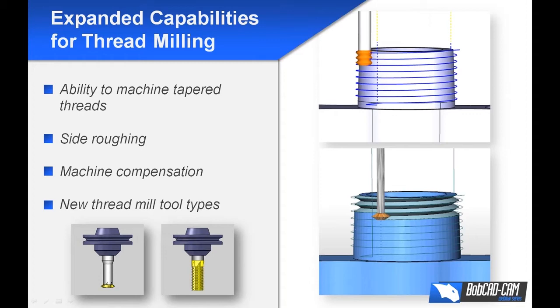All right. Give me one second. We have a question that's already in V5. You can select the solid from drilling. Yes, you can select the solid for drilling, but it doesn't break them down into multiple sequences. For example, if it's the same diameter hole and the same depth, but they're on different Z-planes, like we had there where one was about an inch lower than the other, it doesn't auto-recognize that in V5. Now it auto-recognizes and allows you to use one drilling feature, even if the depths of the holes are different but they're the same diameter. The software will auto-recognize and process that data for you.